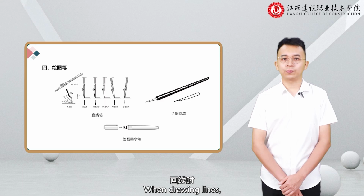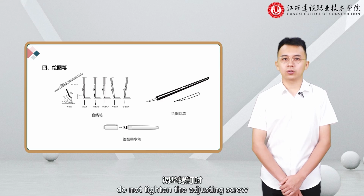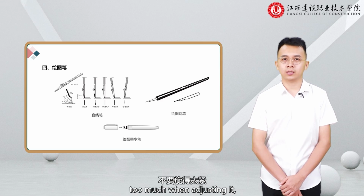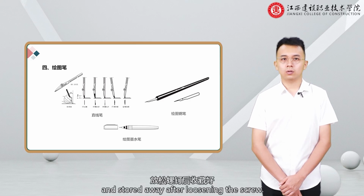When drawing lines, the speed should be uniform, and the force when starting to draw should not be too strong. When drawing thin lines, do not tighten the adjusting screw too much when adjusting it, so as not to deform the steel blades. After use, it should be cleaned and wiped dry, and stored away after loosening the screw.